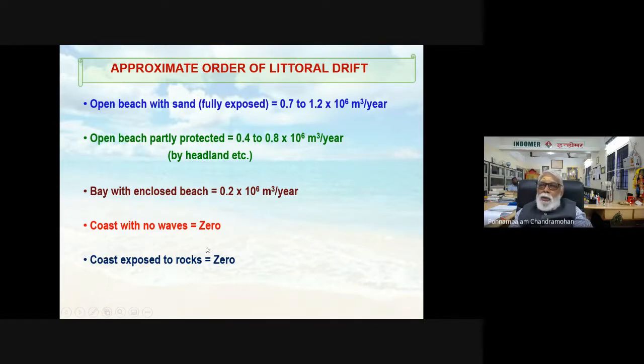There will not be any littoral drift. And also, if you go south of Rameswaram, like Kilakarai and all those areas, there are not many waves, so you will not have littoral drift. Also wherever you have rocks. See, littoral drift is due to sediments moving. On some coastlines you will have only rocks and no sandy beaches, like Kanyakumari. Waves are breaking there, but only rocks are there. There is no sediment system to define littoral drift.